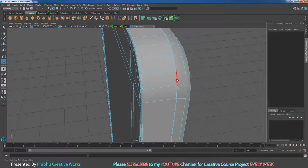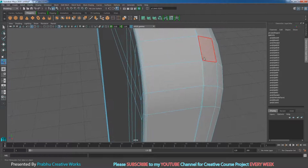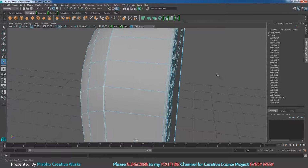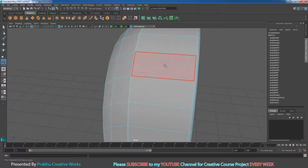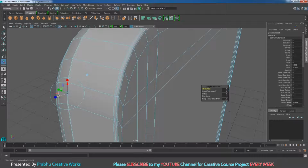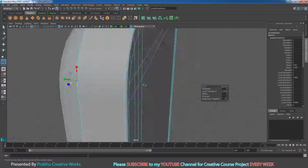So right click and choose face. So select this face, shift and double click on this face. So that means the whole loop will be selected. So see here. So shift right click and choose extrude face. So you want to extrude in Z. So that means it will go inside all the way to.